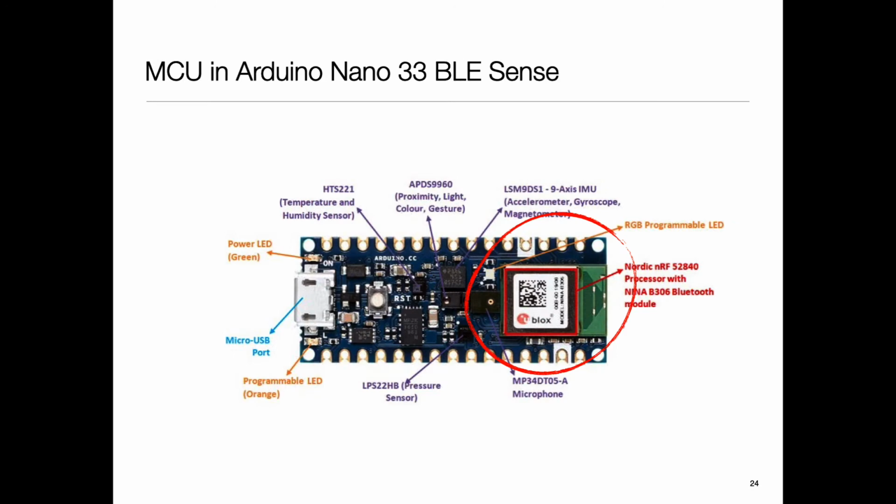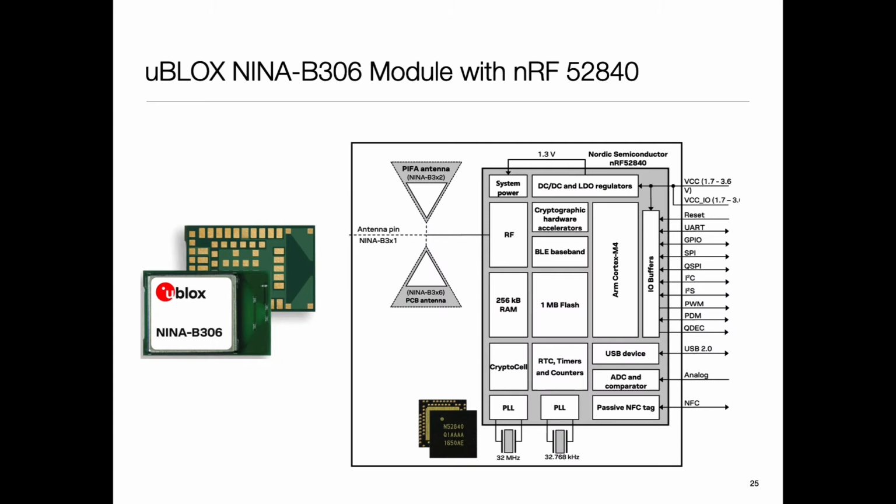The one which I've used in recent years in the class is this Arduino device called Nano 33 BLE Sense. BLE stands for Bluetooth Low Energy. 33, I don't know what 33 stands for. Nano, tiny, and then it has a lot of sensors. So that's the one that I'm using. It's very interesting because, as microcontrollers go, it has one of the higher end microcontrollers with a good amount of sensing, and yet it is tiny. A sweet spot in terms of what it is able to do.